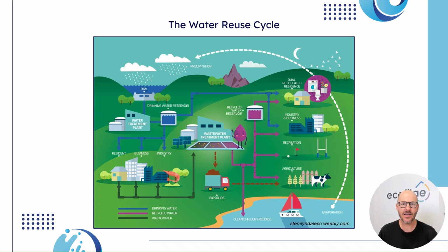By retaining part of the used water from our cities or industries, water reuse secures a part of the water available within the water cycle. It can be integrated into our current water cycle by creating inner loops to substitute abstraction of freshwater from freshwater sources when reclaimed water is used directly for irrigation, industry, or even domestic purposes.